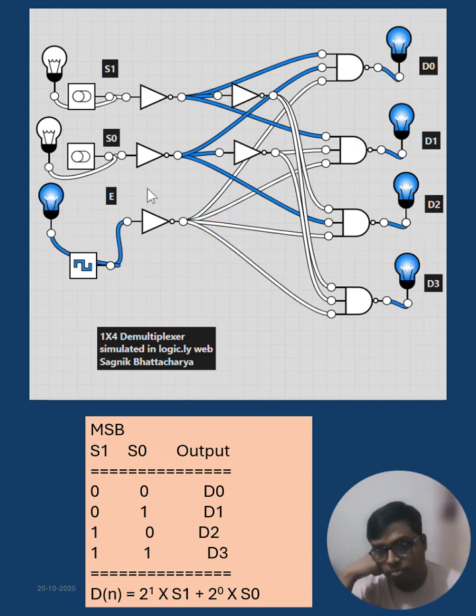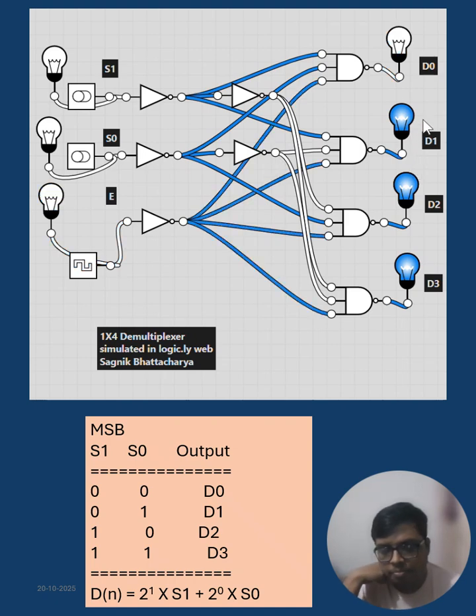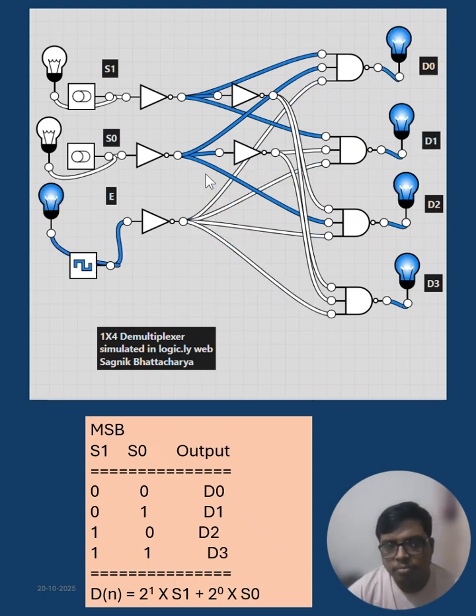How is it happening? First of all, there are three layers of inversion of input. First, all inputs are getting inverted, and in the last stage, you can see this is not an AND gate. This is a NAND gate. Because of this NAND gate, what is happening? The don't care condition, or the unselected switch, that has inverted. So instead of 0, now it is giving 1. But the status will be changed in only one case, that is the selected case. And the status will be exactly the same as, or synchronized with, E.